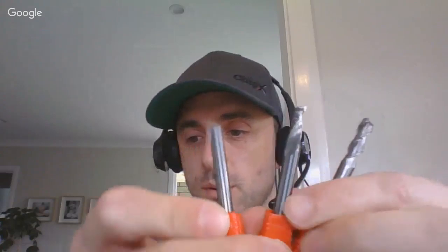We tend to call them tools or bits, cutting tools. There's obviously lots of different styles. I've got a few different ones here, which are for different types of work. You can see a 2-flute upcut end mill on this one here. We've got a single flute upcut in the middle, and then we've got a chamfer mill as well. So different types of tools which will do different kinds of work and which will all have very different feed rate and spindle speed requirements.